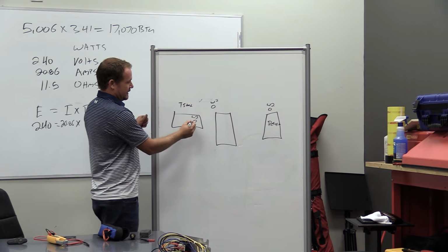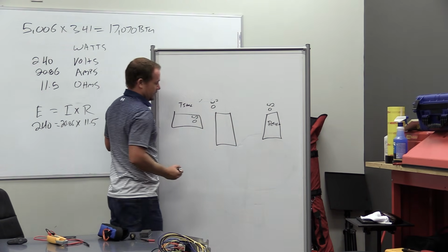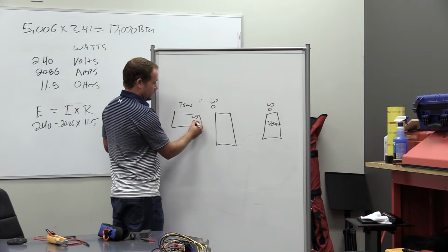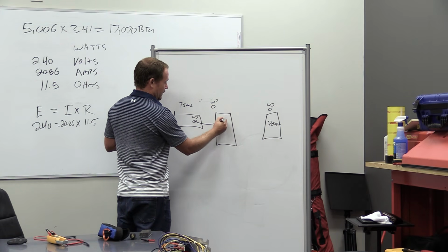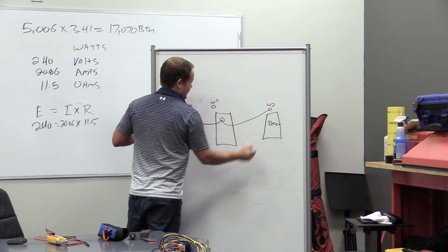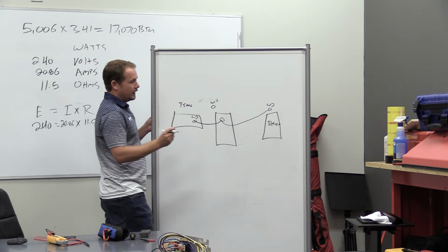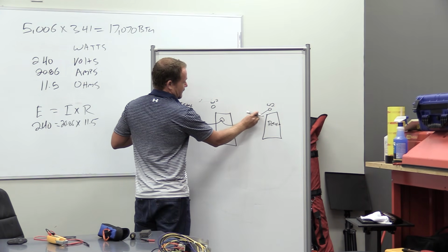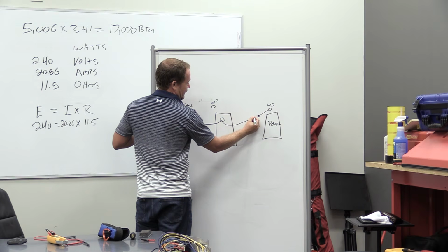So normally we would take this and connect it here and then here. But now what we're going to do is go into our air handler and wire nut together a wire that goes out to here. We're going to break that outdoor thermostat control, we're going to break it here.